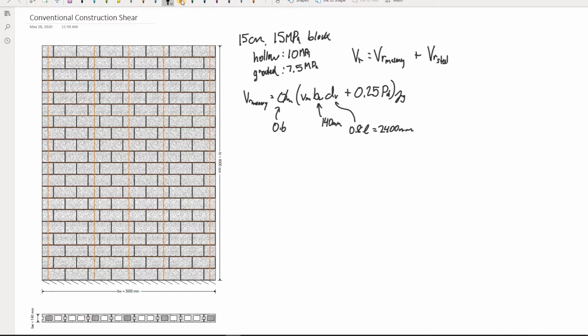And then we have our axial load. For this example, I've just applied a lateral 45 kilonewton load, and I'm going to be analyzing it. The self-weight we can calculate ourselves, but just to speed this along and keep this video from being too long, our axial load, PD, is going to be equal to 25.4 kilonewtons. So that's this term right here.